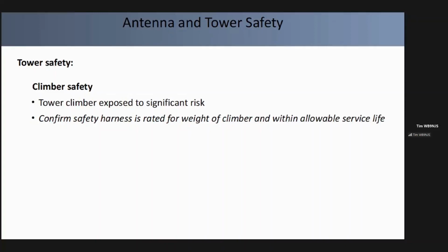That will also have a fall arrest lanyard on it. What you don't want to do is tie a harness off to a solid rope, because if you fall, by the time you've started accelerating and you get to the end of that rope, there's going to be such a shock that alone could be fatal. So the fall arrest lanyards have stitching in them.